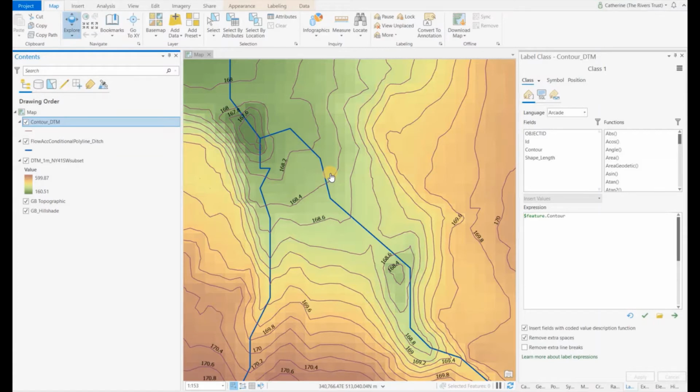So next we're going to have a think about where we want the extent of our pond. We're going to use the natural form of the landscape to do this. So I've chosen this area because it looks like we've got a flattish base and there's a slight natural constriction here that we could potentially place a bund across, and that would back water up into this whole area.